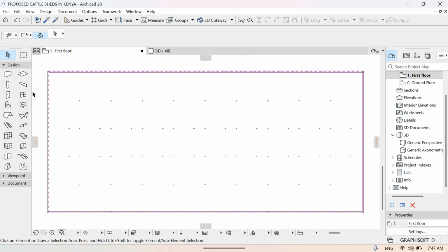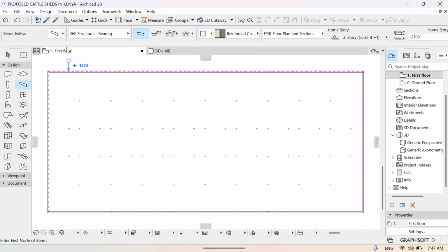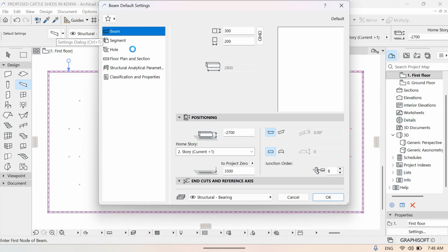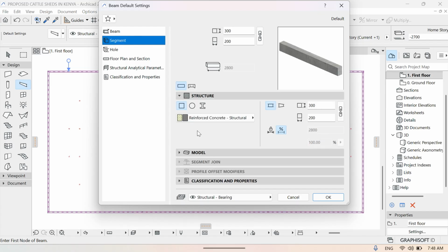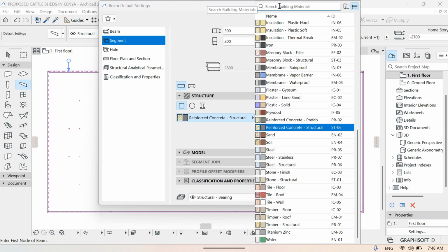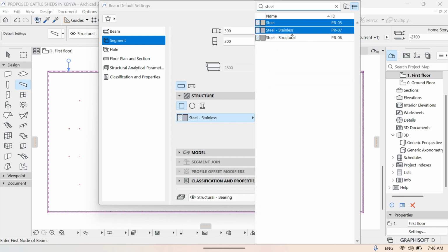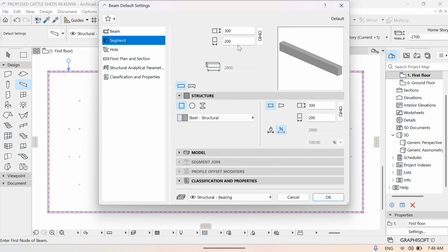Let's go to our design tool. It's still a beam, but now it's a structural beam, a steel member. We're basically using a steel member for a beam, so come to that and tap that. Let's first search steel. There we go, structural steel. And we can use a 3x2 tube. So 3x2 should be 75 millimeters, and the width and the bottom bit to be 50 millimeters. That should be good enough.